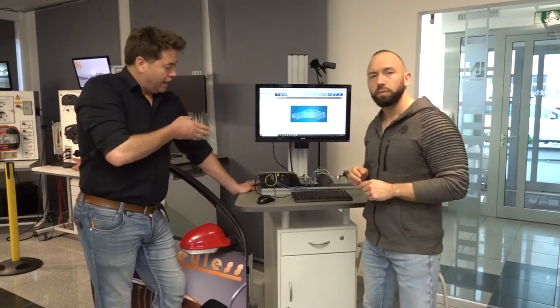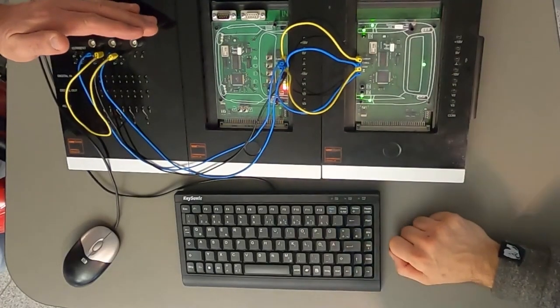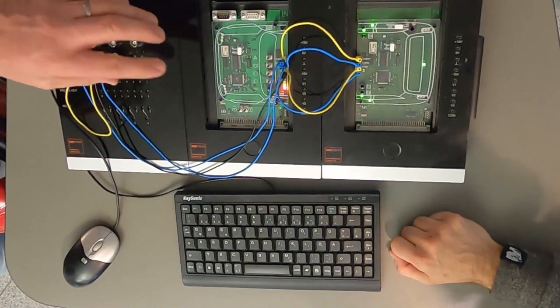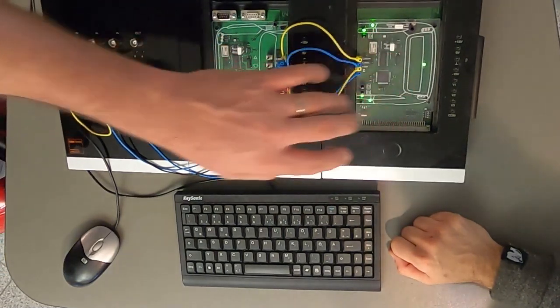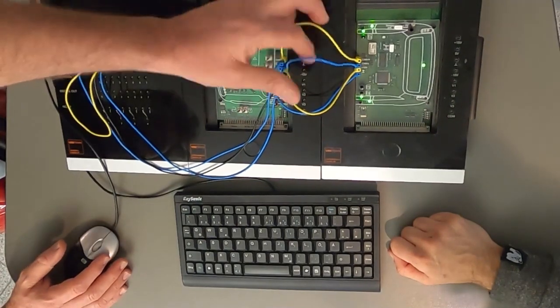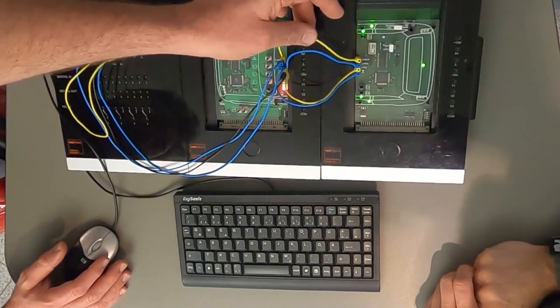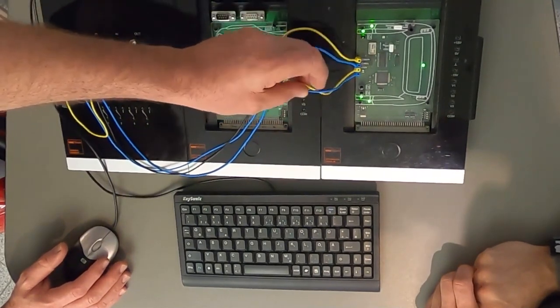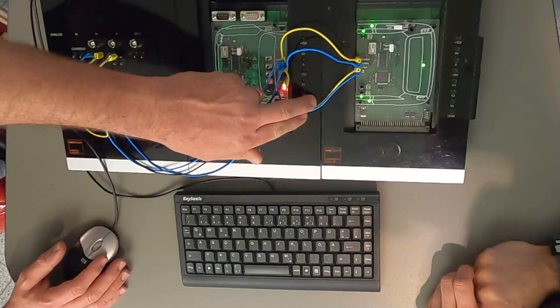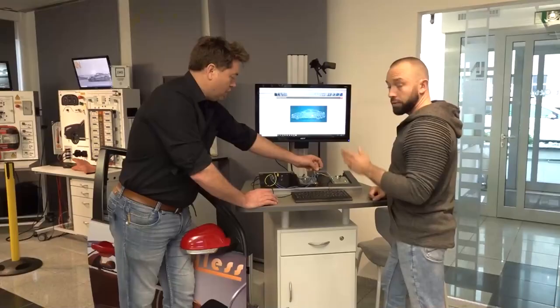Okay, so we'll have a look at this system here. This is our Unitrain system. You might have seen it in a lot of our training videos before. And we've got these cards here, which is our CAN bus course. You can see there's 4 wires on the system right now, and the system is literally running over these 4 wires. So we have a positive and a ground, so that's obviously our power supply, and then we have our CAN high and CAN low here as well.